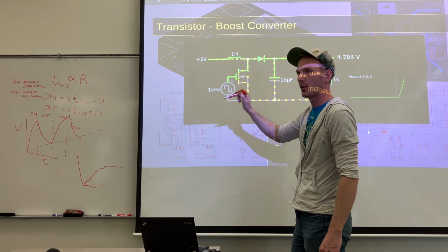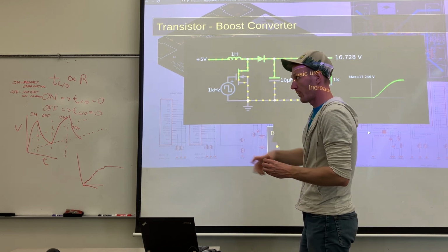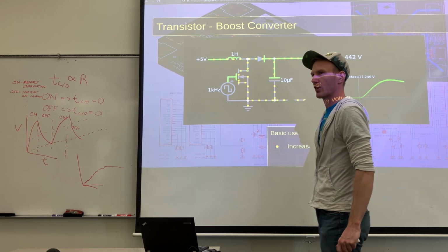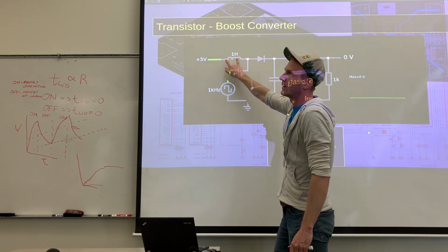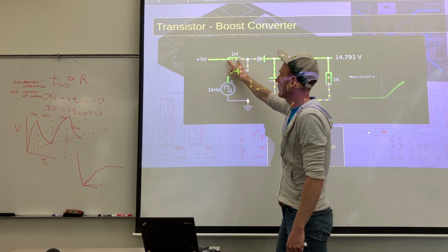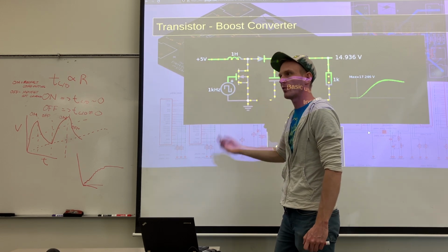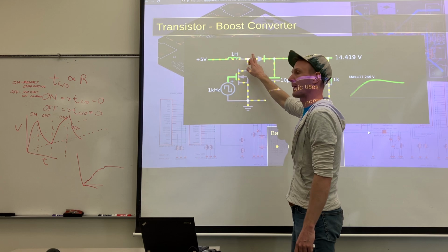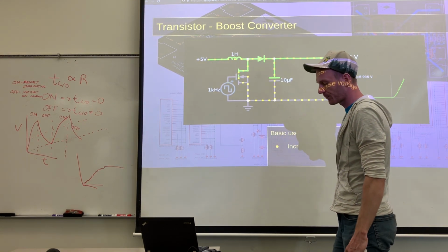Because the inductor is resisting a change in current, initially, we sort of covered this on the first day, we sort of didn't. If you look at time 0 on this, you're supplying 5 volts and this is dropping 5 volts. It is using all of the power you're supplying to it and it is allowing almost no current through this whole process while it's building the current up.